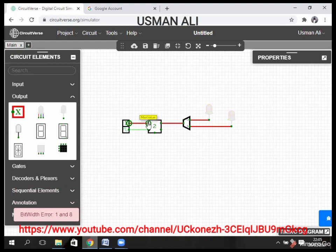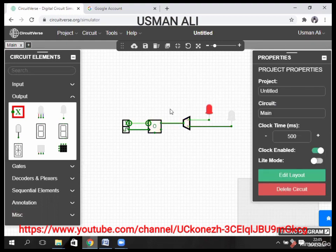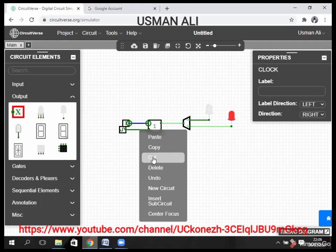Connect our output here, the max value. Now click on the counter and change the bandwidth. Bandwidth is 8. You have to make the bandwidth 1 because we need two values, 0 and 1. Here is 0 and here is 1. So with enter, you see it starts working. Cut down the clock a little bit.